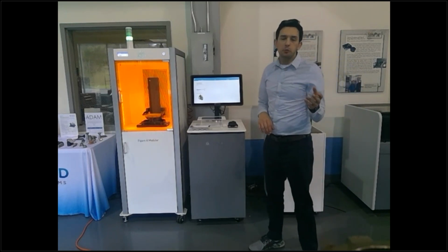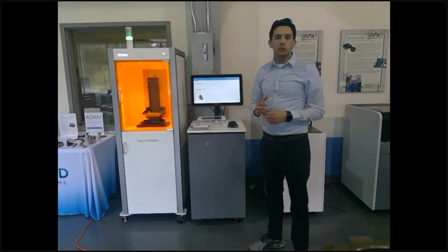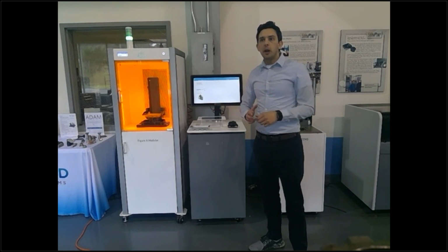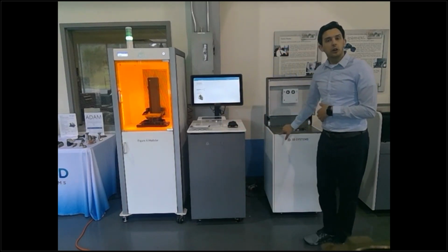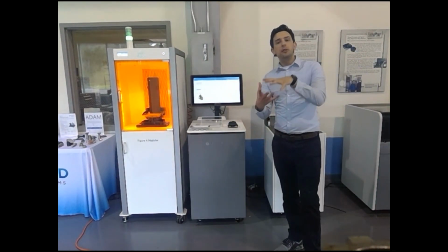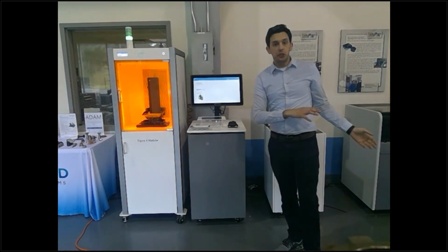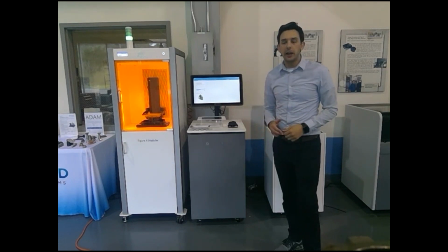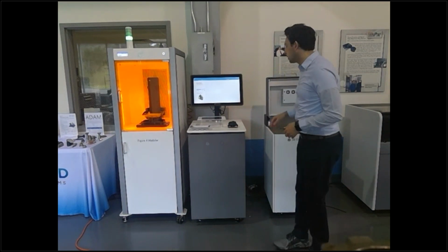Pat had mentioned post-processing parts that have support material on them. And there's kind of two routes you can do that. Depending on the geometry of the part, sometimes you might want to remove support material before you put parts in the UV cure oven. Other times, like if you're printing a full stack, you would just leave all those parts stacked together. Post-process and cure that stack in one piece, and then remove all of the parts individually off that stack. So again, it's just nice 3D Systems gives you some options for how you want to post-process parts.